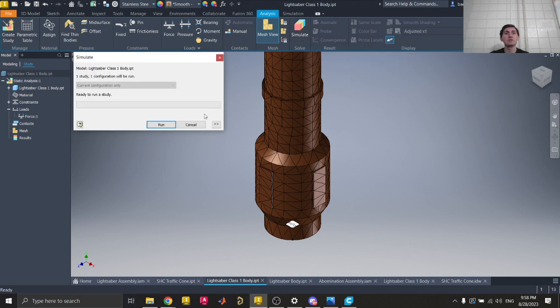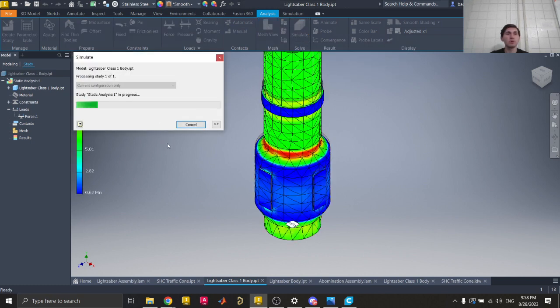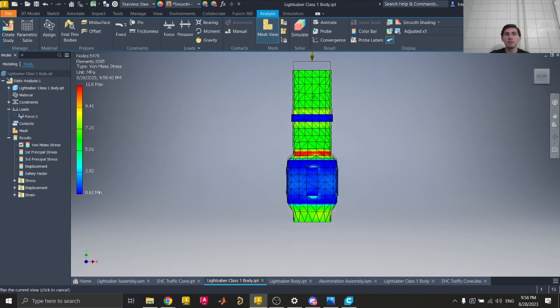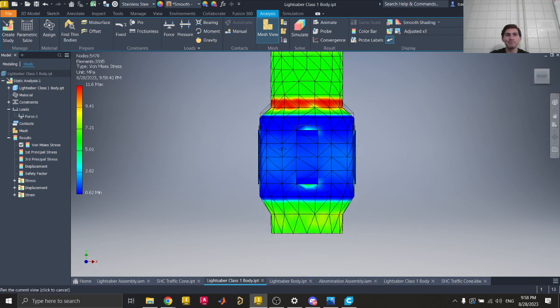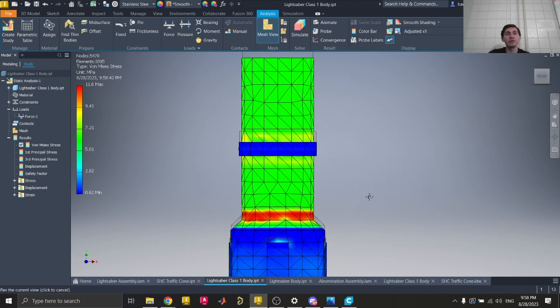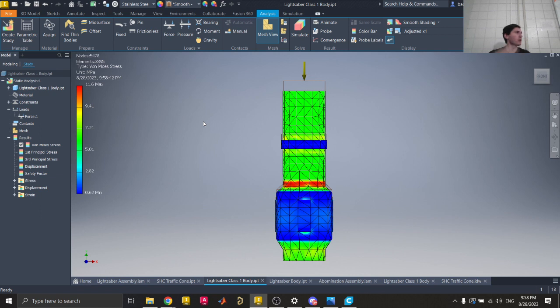And then let's just hit simulate. Let's hit run. Give it a second. Then bam, and then you can see you need to reinforce it more. Use a stronger lightsaber. I don't know if you'll ever witness 15,000 newtons. But yeah, you can do that. You can add torsional loads. You can do whatever. If you want to do modal analysis, like vibration stuff for a spacecraft structure, I've done that. It'll find all of the resonant frequencies of the thing.